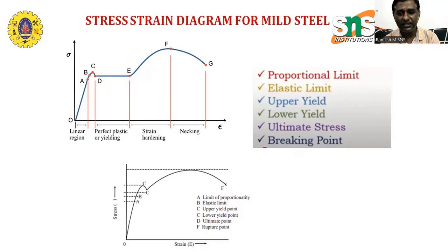then it attains the elastic limit. Up to this, Hooke's law is valid. Beyond that elastic limit, Hooke's law will not be valid, because Hooke's law says stress is directly proportional to strain. So there will not be a linear line beyond the elastic point; it will be a non-linear one. After the elastic limit, you will have a yield point where we can have deformation with no increase of stress value.